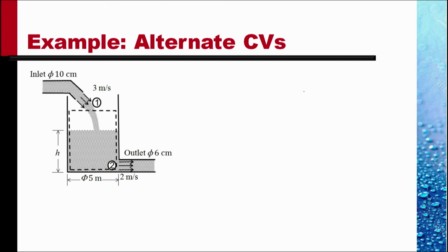But when we find the flow, only the vertical component of velocity would contribute to flow across that area, and the vertical component of velocity would be v times cosine 45 degrees. So the product of the velocity and area would still be the same, VA. So we should get the same result.